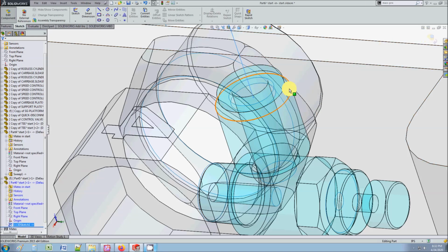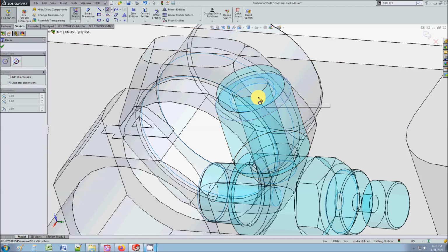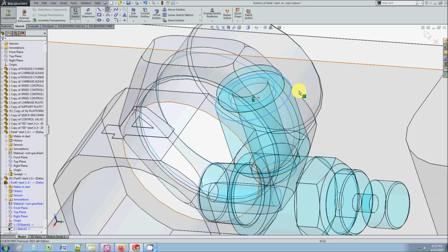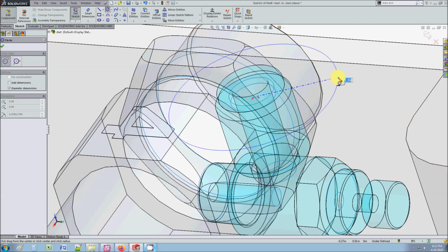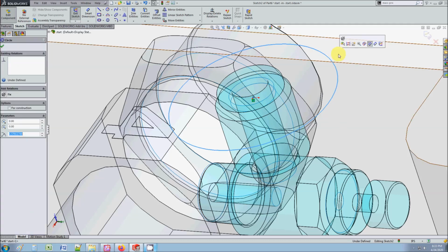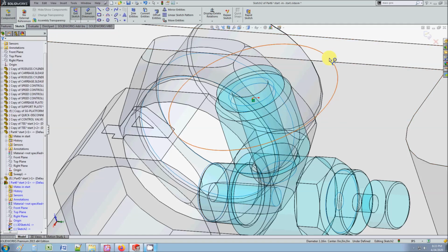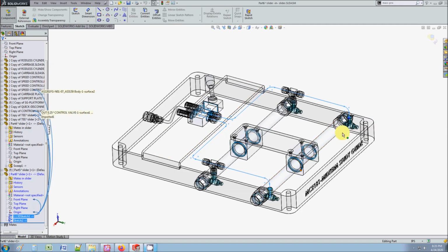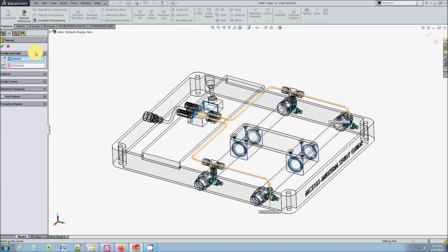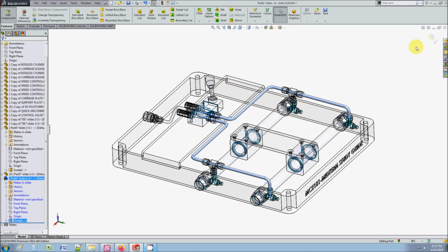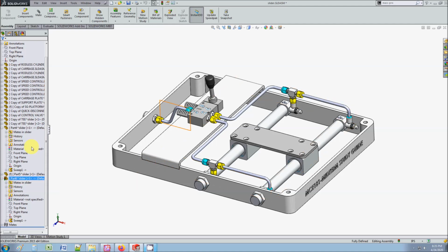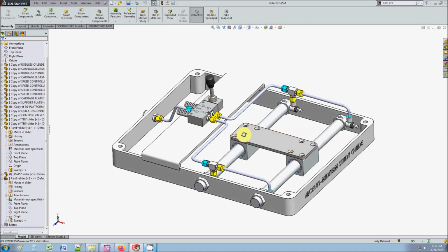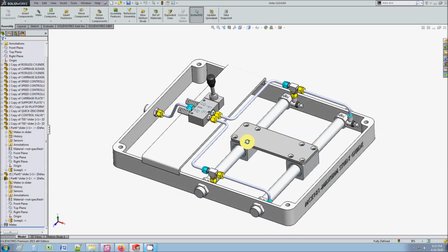So I'm going to create a circle now on that surface. And it's probably, ooh, no, I don't want that. It's probably gonna be maybe 0.25. So here's the tubes, and we're gonna click on swept boss base so we get a profile here. So there's the tube, and there it is. So I'm gonna save. Okay, so now that's good.